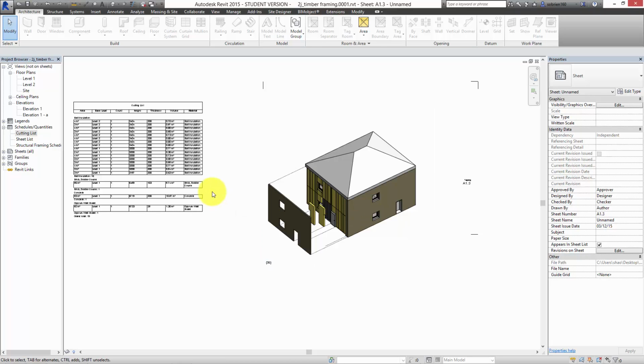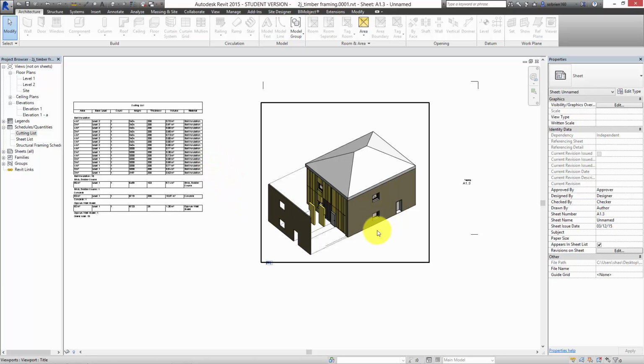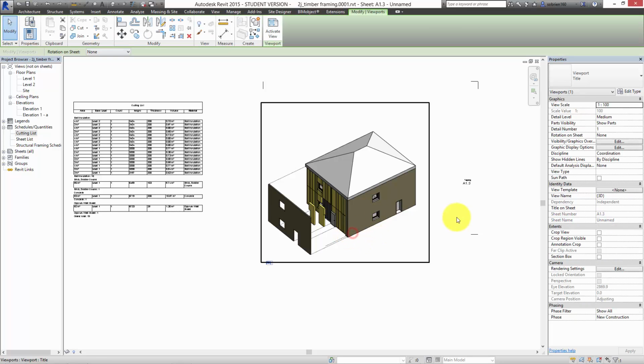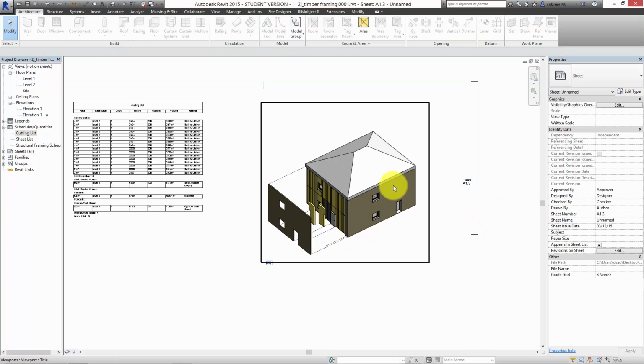Remember this is almost more detailed than you need, because just by using the walls itself, it already calculates the volume of insulation in the wall, and that's usually enough information. It's only when you're getting right down to a very specific element that you need to get so specific about parts. If I did a wall schedule, for example, I could calculate the insulation in all the walls in here, but it wouldn't divide it into cutting lists.